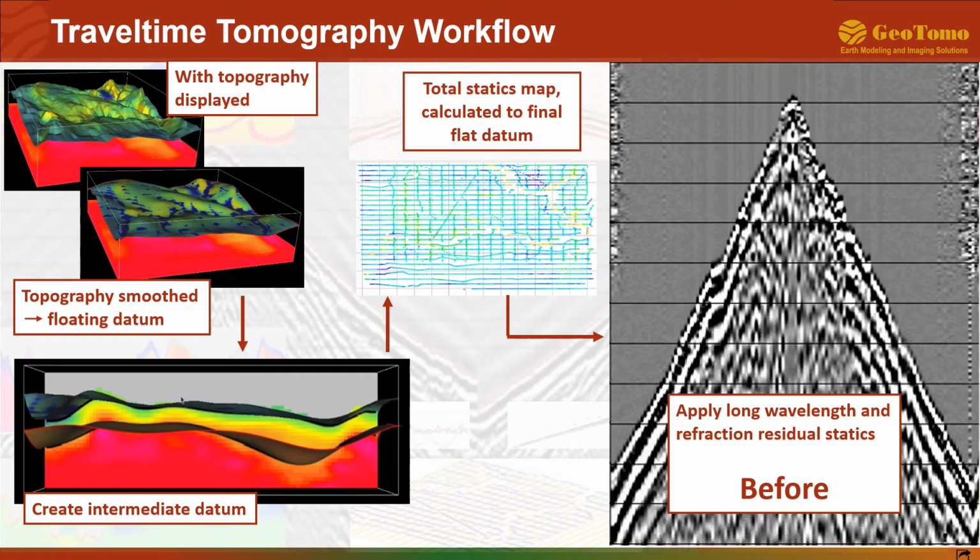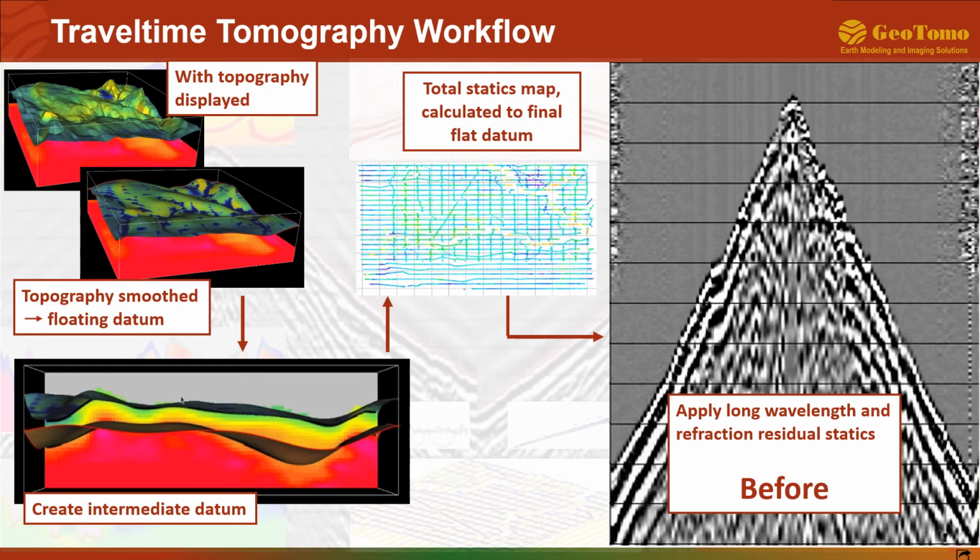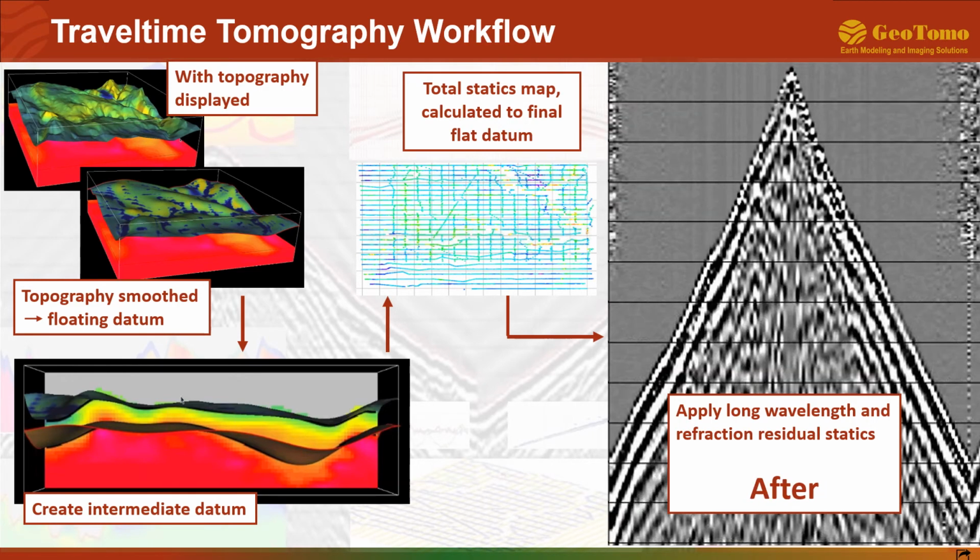Here is a shot gather before application of total statics. And here is the shot gather after application of long wavelength and refraction residual statics. Before statics applied and after.